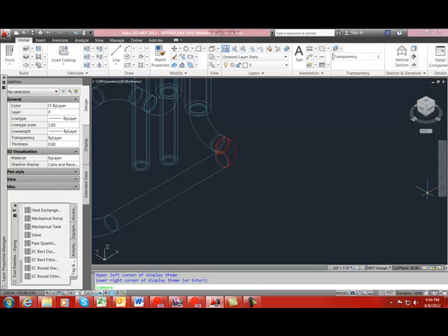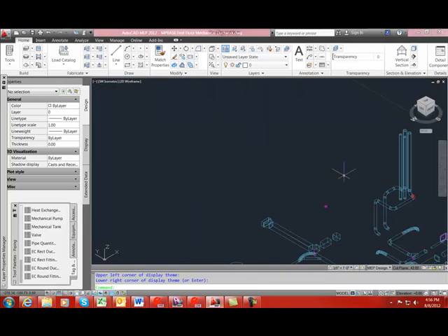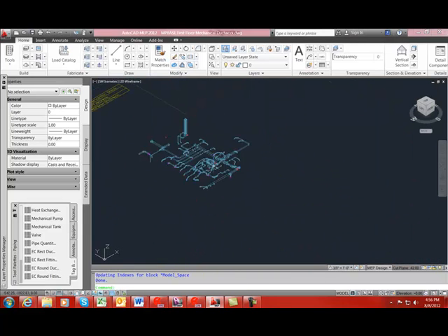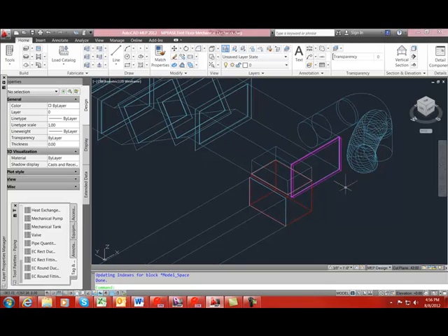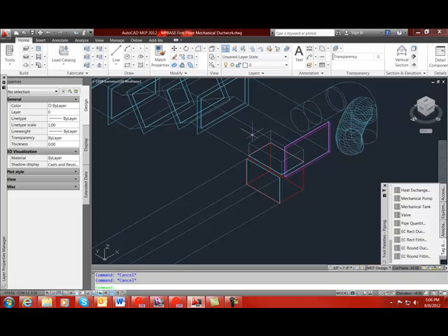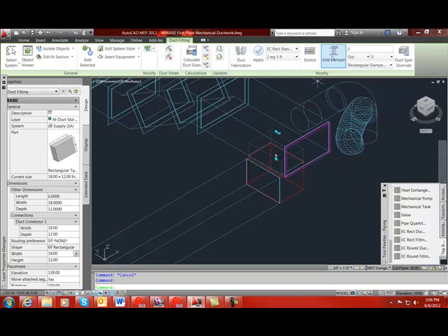The first one we'll take a look at is the rectangular square elbow. What we want to do to fix this error is first set the tap and square elbow to free defaults to make all parameters available for editing. We're going to select the tap, go up to the ribbon where it says EC Rect Standards, and switch it over to EC Rect Free.